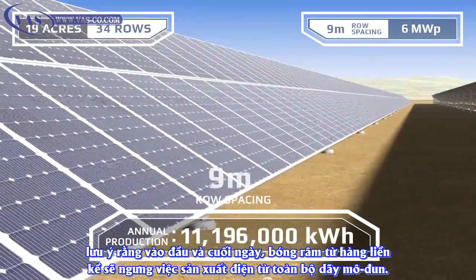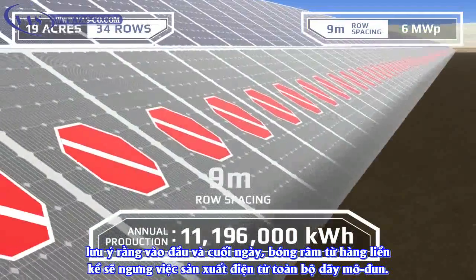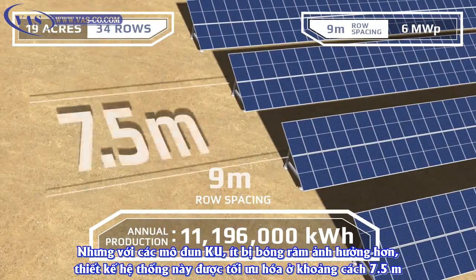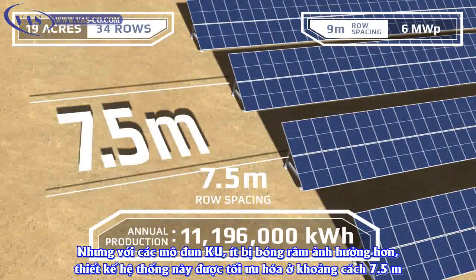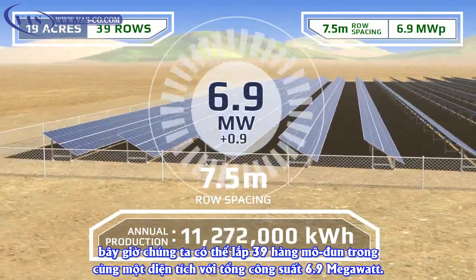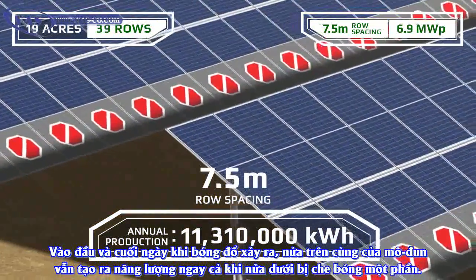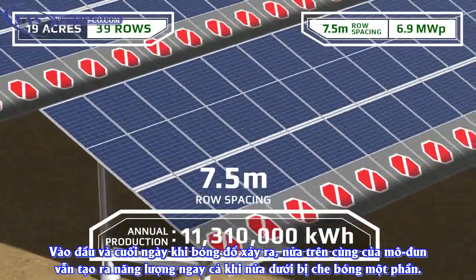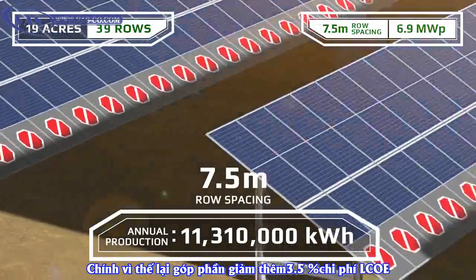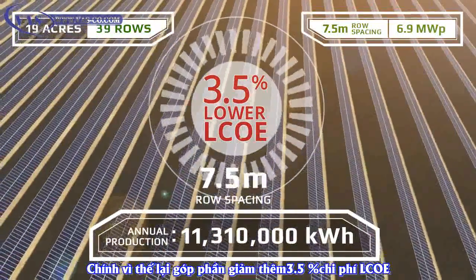Notice that at the beginning and end of the day, shading from the adjacent row knocks out power production from an entire row of modules. But with Ku modules' better shading tolerance, the system design is optimized at 7.5 meter spacing. Now we can fit 39 rows of modules in the same parcel for 6.9 megawatts total. At the beginning and end of the day when shading occurs, the top halves of the modules are still producing power, even when the bottom halves are partially shaded. Factoring in the additional equipment cost, Ku modules deliver a 3.5% lower LCOE.